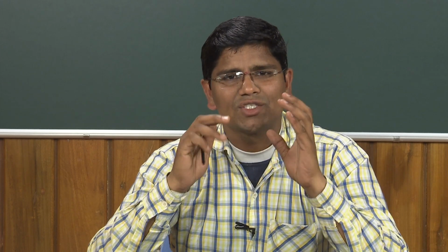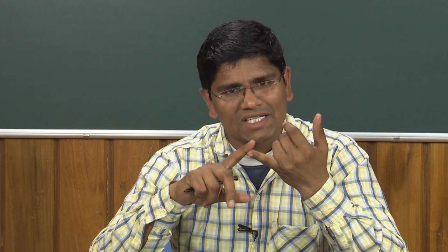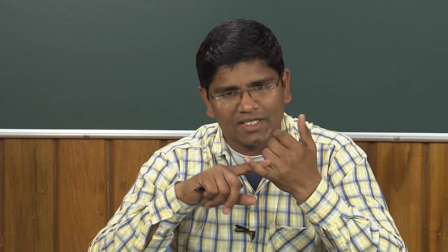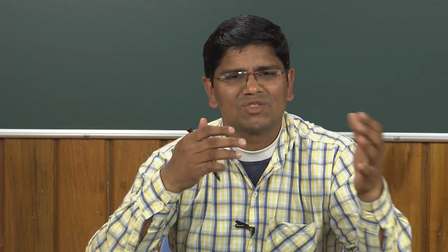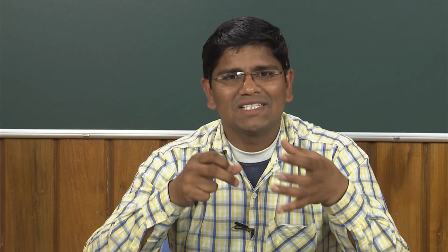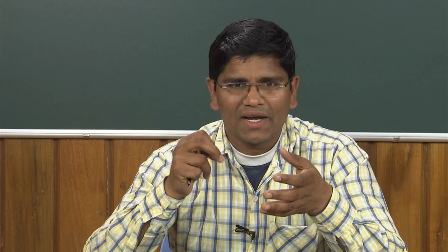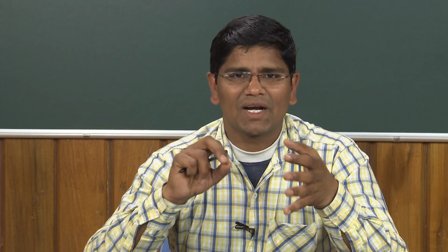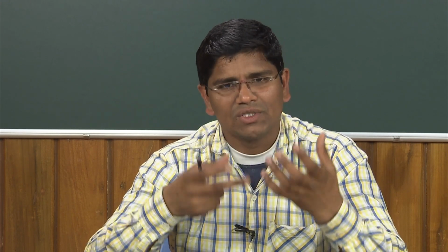Today's lecture is more informative from the point of view of research. Those people who are interested in taking up research can do so using their own bio cutting fluids. You know what the bio cutting fluids are, since I have talked in many lectures about the oils. You can play with the oils, you can mix the oils based on thermal conductivity. You can take a KD2 probe, measure the thermal conductivity of different cutting fluids, and you can generate your economic way of nozzles and use it.